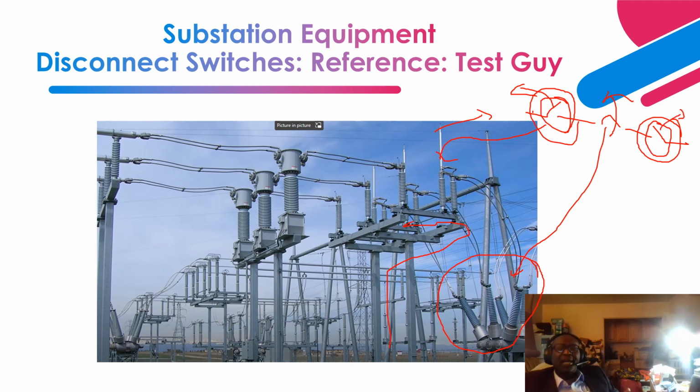They've been designed so that there is an amount of capacitive charge and current that they can break, let's say about 0.5 amps. As you can see, there are a lot of insulation systems in the substation, and based on that there is something called stray capacitance, which is invisible; you don't see it. So the no-load operating disconnect switches have been designed in such a way that they can break this amount of capacitive charge and resultant capacitive current that occurs due to this stray capacitance to ground.